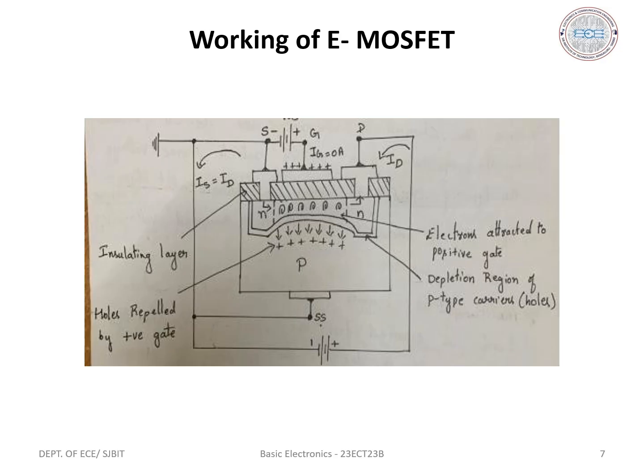So what they do is start accumulating near the oxide layer. That layer is called an inversion layer here. This inversion layer will act as a channel between the source and the drain terminal. Now when VDS voltage is applied, then current, that is ID, is created and can flow in this channel.